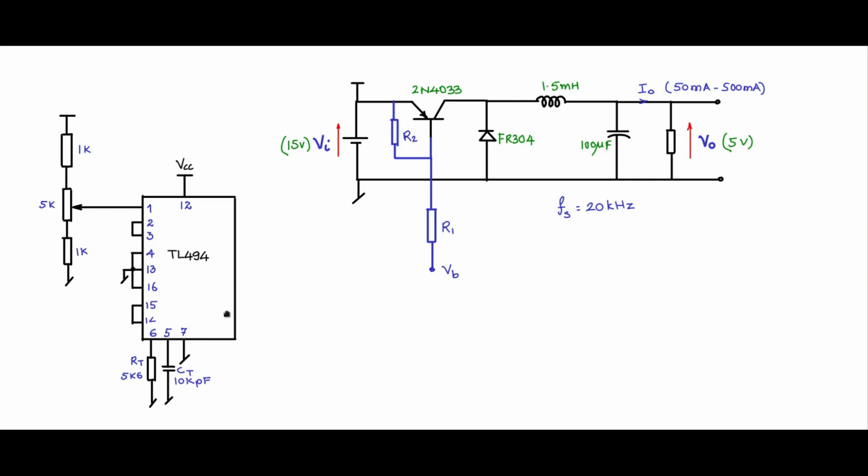Now that is 15 and 14. Internally there are two transistors that will get enabled or disabled depending upon the pulse width modulated waveform that is coming to the base of these internal transistors. So this is pin 11, 10, 8 and 9. You can use any one of the transistors. Now let us say I use this 8, 9. 8 is the collector, 9 is the emitter.